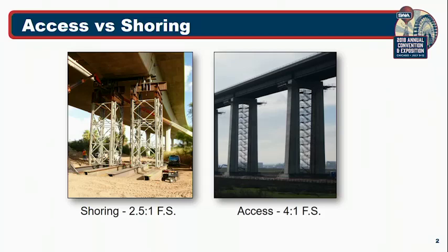For example, a typical 3-foot wide access scaffold frame in a 4-legged tower configuration can support loads ranging from 12 to 20,000 pounds. In comparison, modular scaffolds, depending on the manufacturer, can support loads ranging from 20 to 60,000 pounds. When looking at a standard heavy-duty shoring frame, those are actually good for about 40 to 50,000 pounds. And so a lot of times, our modular scaffold systems are actually stronger and more versatile because you guys have different ledger lengths and even cross-bracing lengths handy in your yards, and you don't need to outsource them.